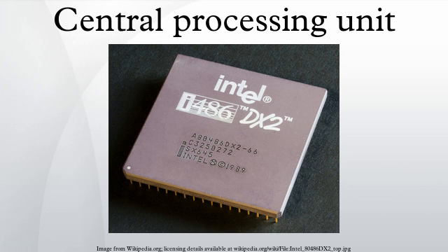Another method of addressing some of the problems with a global clock signal is the removal of the clock signal altogether. While removing the global clock signal makes the design process considerably more complex in many ways, asynchronous designs carry marked advantages in power consumption and heat dissipation in comparison with similar synchronous designs. While somewhat uncommon, entire asynchronous CPUs have been built without utilizing a global clock signal.